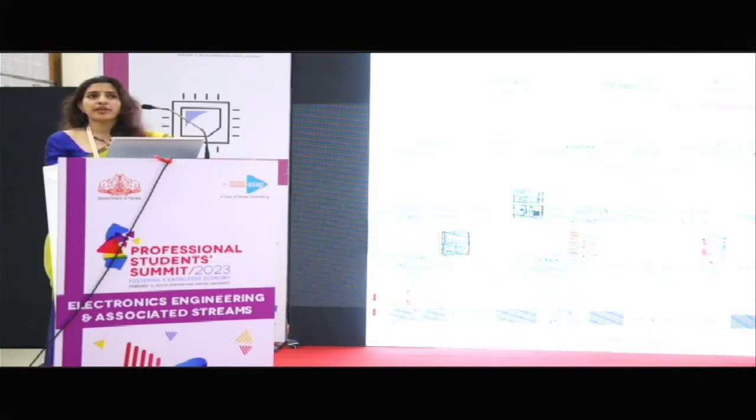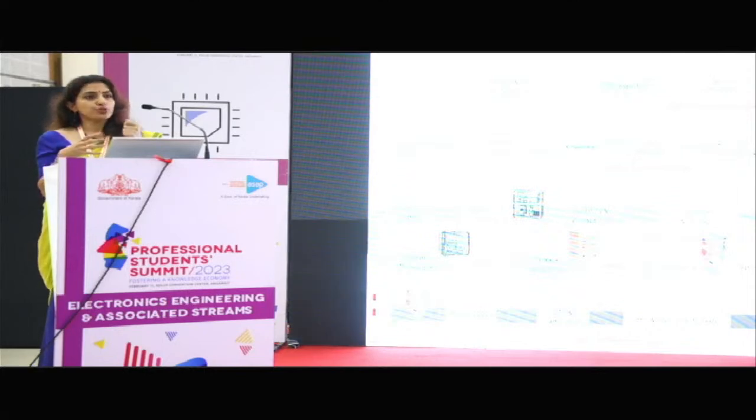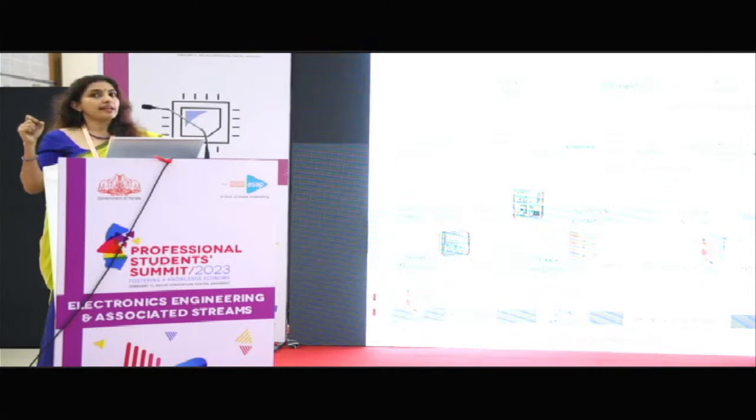First, start with the component. There are different grades of components. In colleges you will be using normal commercial grade components. Then there are industrial grade components, launch vehicle grade components, and satellite grade components. When you design a satellite, it is very difficult, because as a design engineer you will have a particular design in mind and you will choose certain components for that, but those components will not be available in the satellite grade.